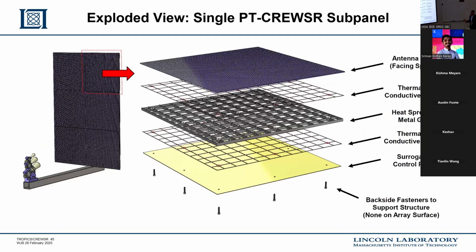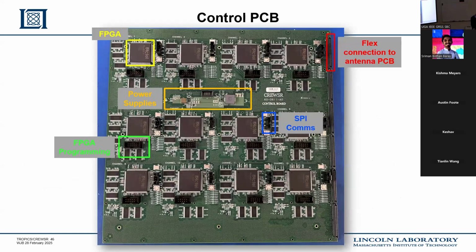So here's just a little bit of insight into how the panel is stacked together. Again, we're trying to keep the panel flat. We're trying to deal with thermal effects, trying to deal with radiation effects. So these are a couple of things that help us do that. We've got various materials of stack up, heat spreaders, epoxies, to keep everything attached and flat. So very careful analysis and planning has gone into choosing how we architect that panel, the materials that we choose, how we bond things together, and that's worked out really well.